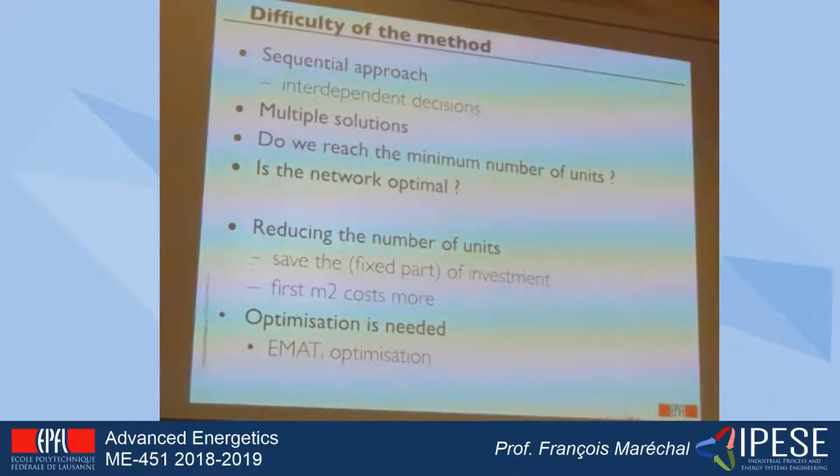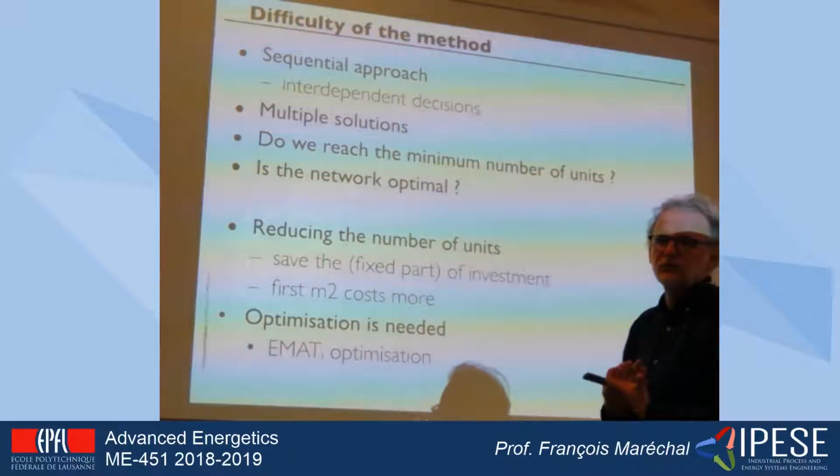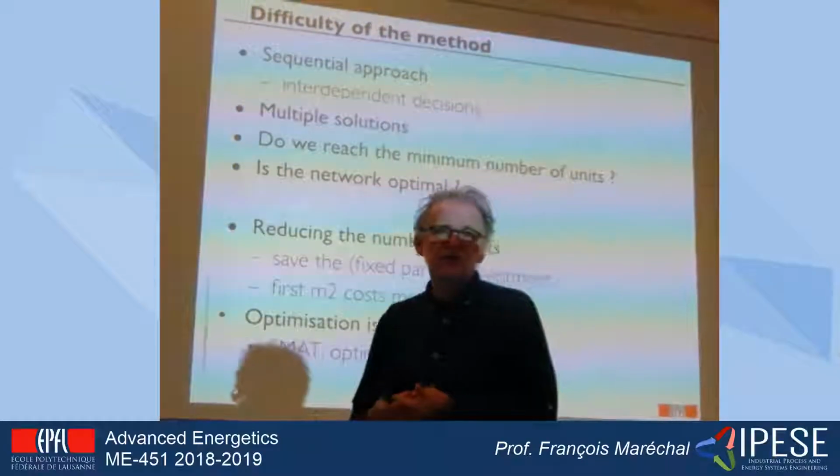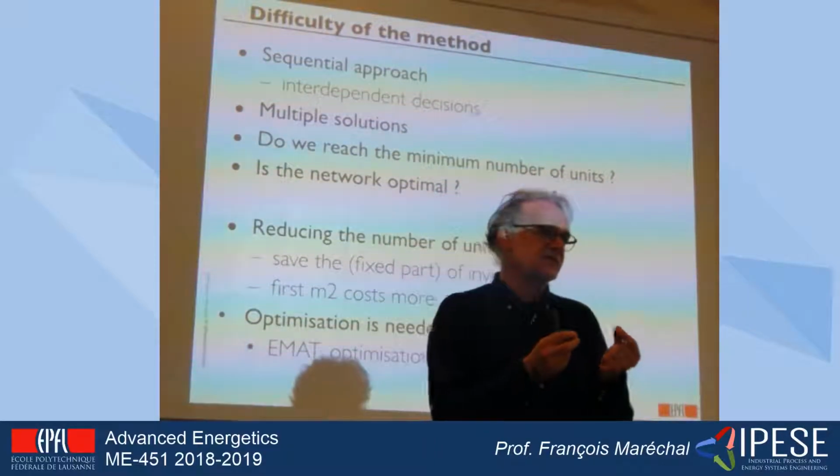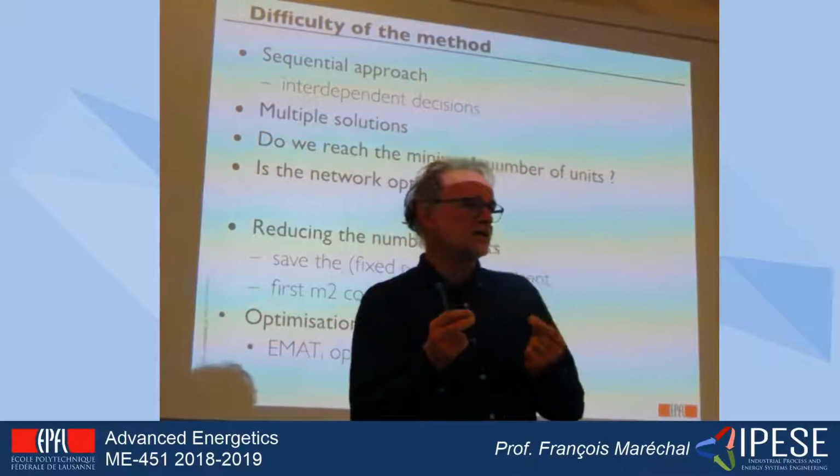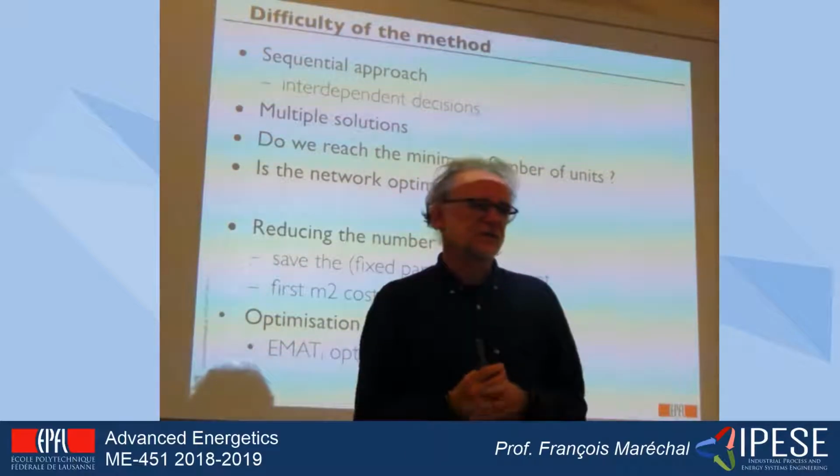Systematic methods allow us to see if we can or not remove heat exchangers by applying either the loop identification or the path identification, which gives us a first guess of the most attractive solutions to be compared, knowing that if we want to be really rigorous, we have afterwards to apply optimization methods to define the best size of each of the heat exchangers inside the system that we have designed.